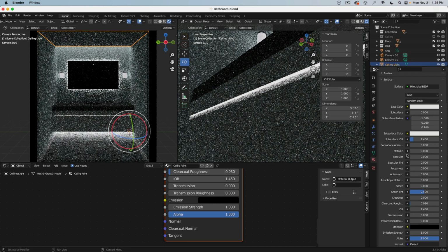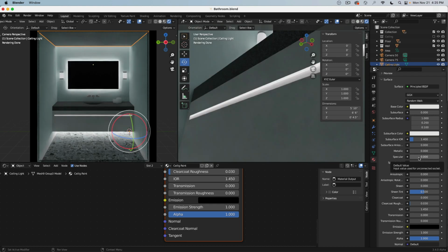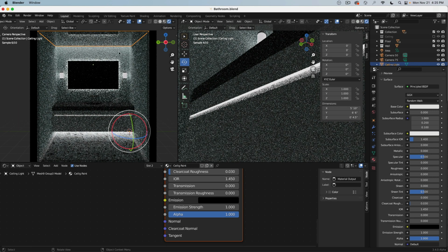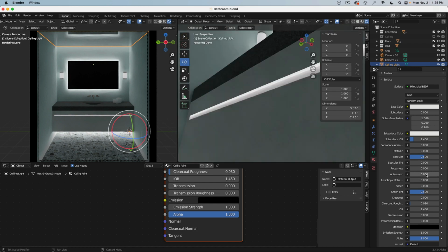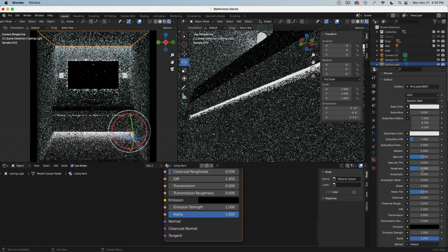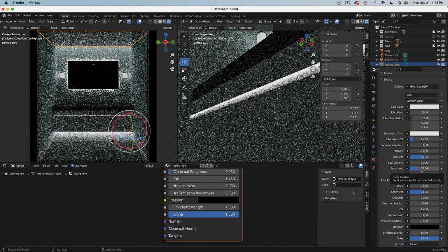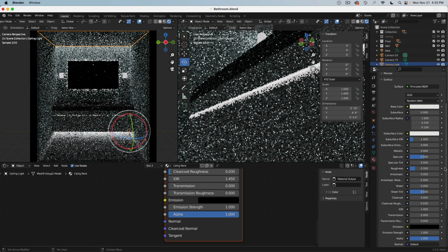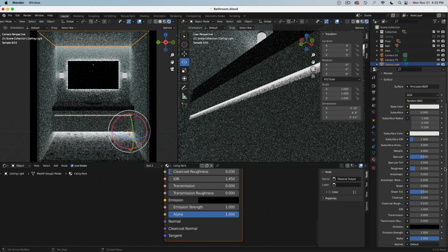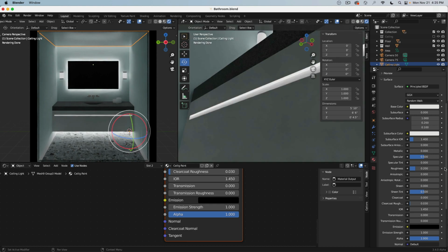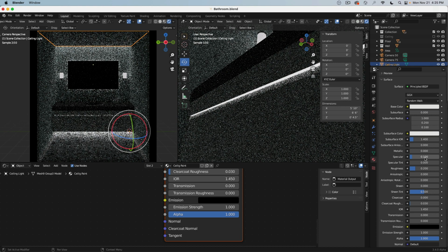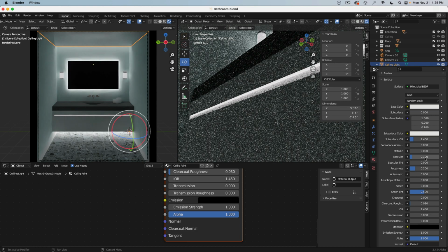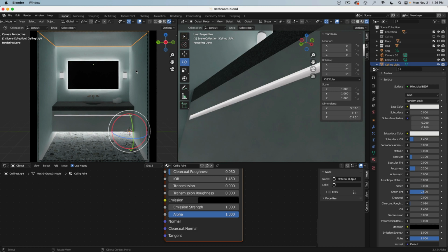Okay. If this should be kind of like a little bit painted, maybe plastic. Now it's reflective. Now you can see, oh, it's actually pretty glossy. And then the roughness, 0.3. That adds a little bit of blurriness to it. 0.2, okay. And obviously, such a paint has a little bit of shimmer to it. The reflectivity is not as strong. 0.1 maybe. Or we can lower this till this feels like this is kind of good.